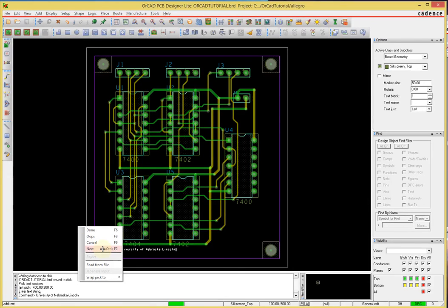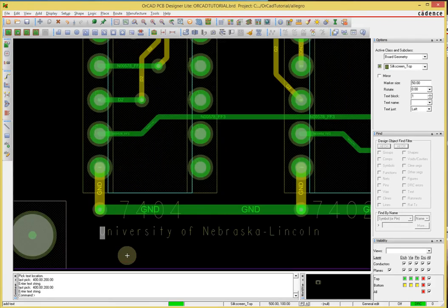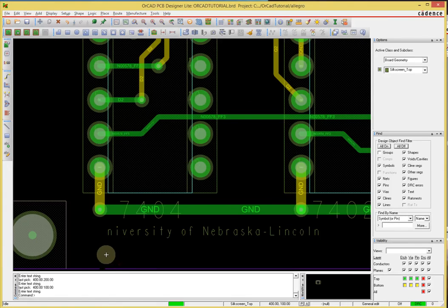Okay, again, we want to do next. If you want to add more text, you can't just hit enter and then have a new line. We need to add more information. Maybe let's click over here. Oh, my grid spacing. Once again, that grid spacing. Let's do a done. Notice that my U disappeared. Sometimes there's some weird graphic that needs refreshing. You can hit F5 to refresh the graphics.